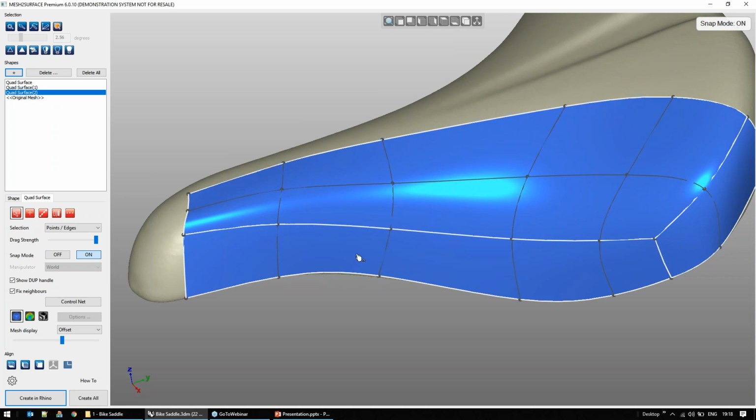Why is this important? Because during Boolean operations for the cut, it's vital to have surfaces that don't join together but are one surface. Then all the Boolean operations work much faster, and the file size is smaller.